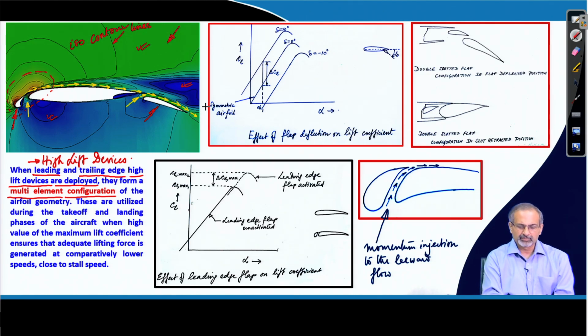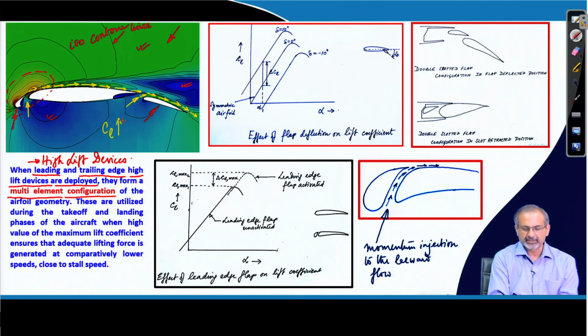And from the flow features we find that there is no large scale flow separation like effects that we can see over here. We do not see very large eddies, reverse flow or recirculating flow, etc. So, that basically means that this is indeed generating substantially high lift. One more thing that you can figure out is that the flow perhaps is coming in at an angle over here.